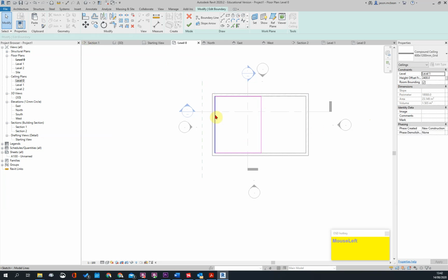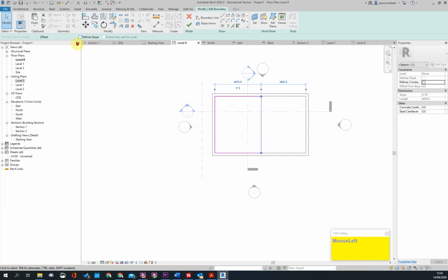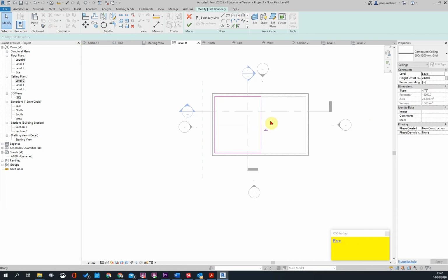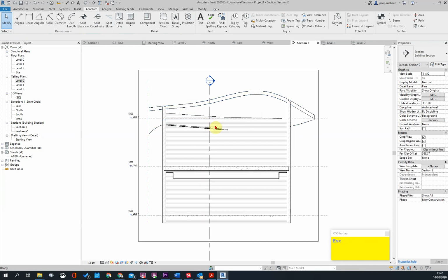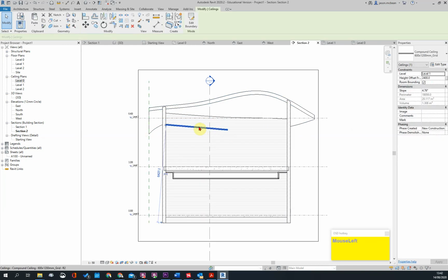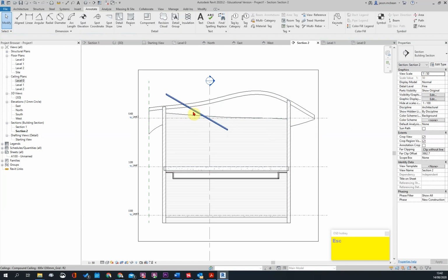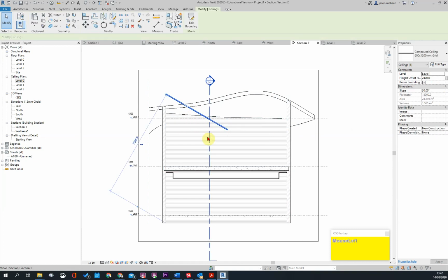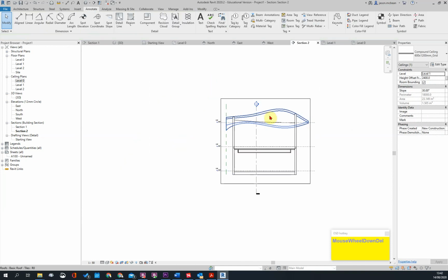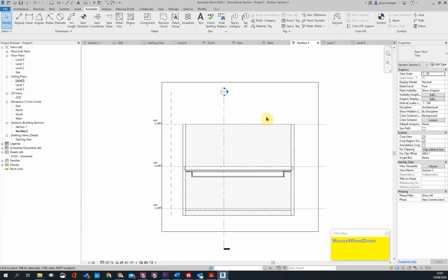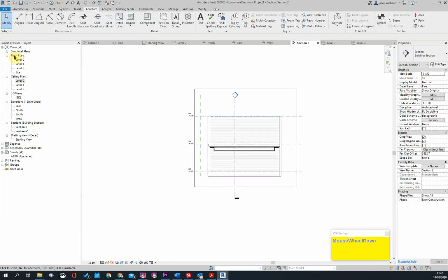Okay, so here you need to pick an edge that it defines the slope as well. So here you can say define slope. So this is your slope, okay? And it'll slope in that direction. So it goes in that direction. Okay, slope 30 degrees. So then you can make it follow your ceiling. Okay. So roofs and ceilings will have slopes. And okay, one last thing I just want to show you regarding roofs. So let's make one last roof.